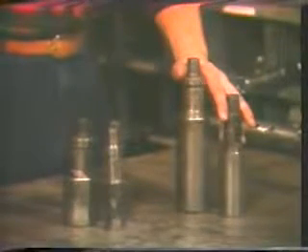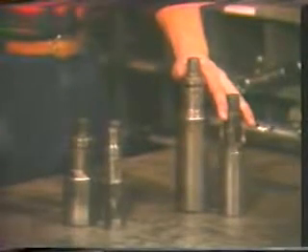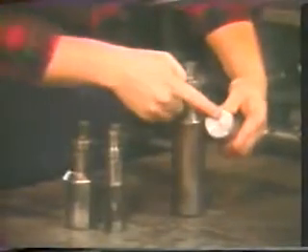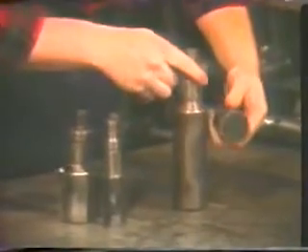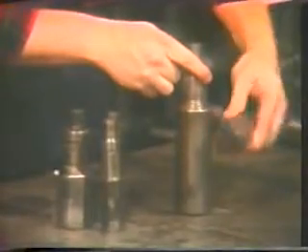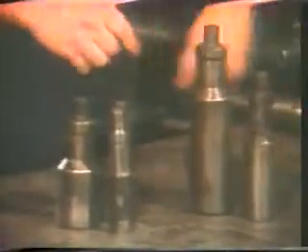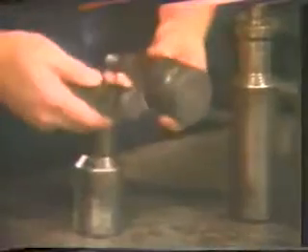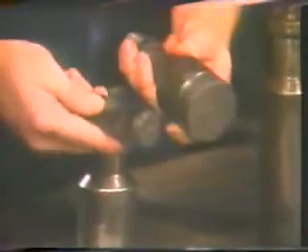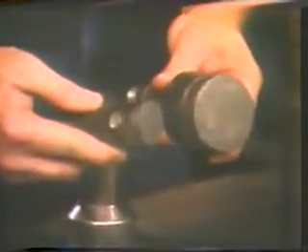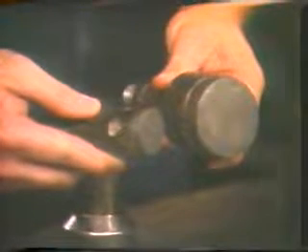The blind box is a solid metal tool used to hammer down on an obstruction when heavy downward jarring is required. It could be thought of as the head of a wireline specialist's hammer. The tool surface is flat and hardened, so it will not flare out on the bottom when it is being used to hammer on tools or other obstructions in the tubing. The impression block is used to take impressions of hard or metallic objects in the tubing in order to determine their size, shape, and relative position in the tubing.